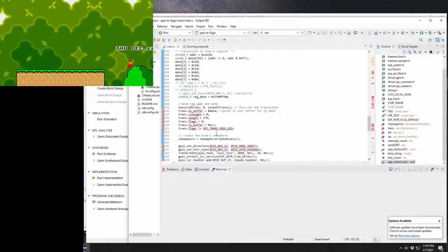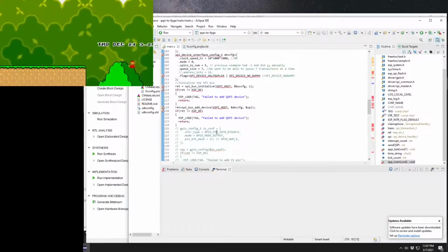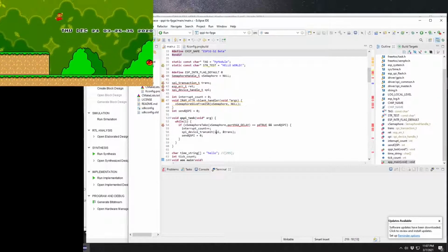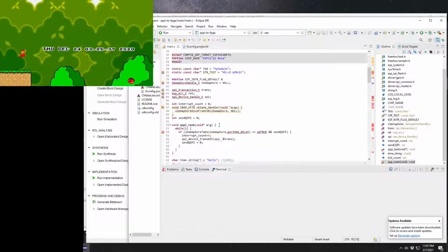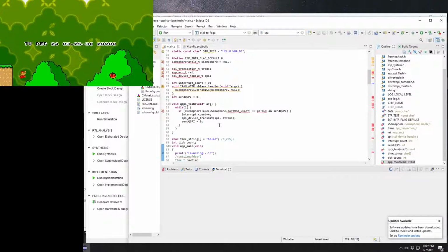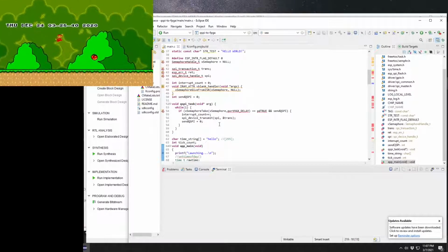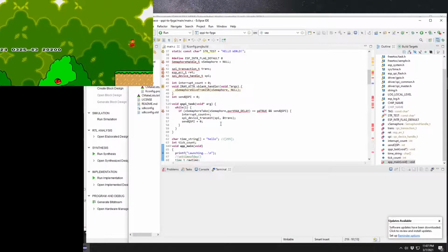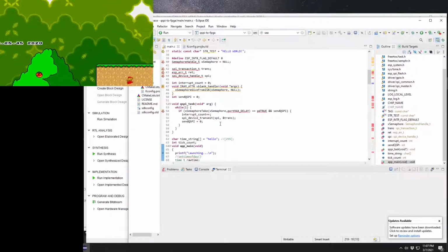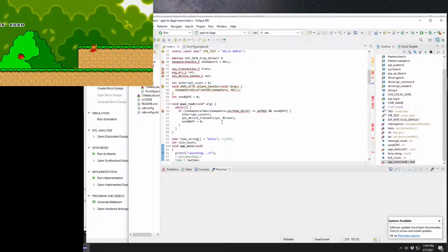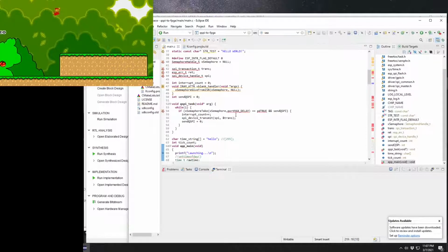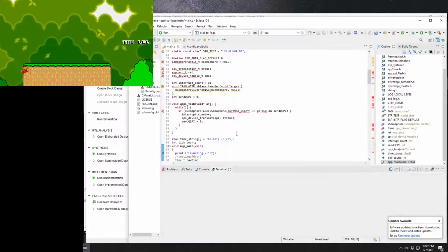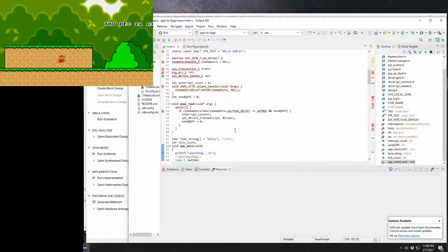One important thing I had to learn here also was how to send data using interrupts. In this application on the ESP32, we're going to wait until we get a signal from the FPGA that it has entered its blanking period. So the FPGA will not be reading anything from memory, and that's when it's safe for us to write new data to memory. Again, this works very similarly to how the NES and the Super Nintendo work, and I think a lot of other earlier gaming systems would send updated data to VRAM during the blanking period. So that's what we're doing here as well.